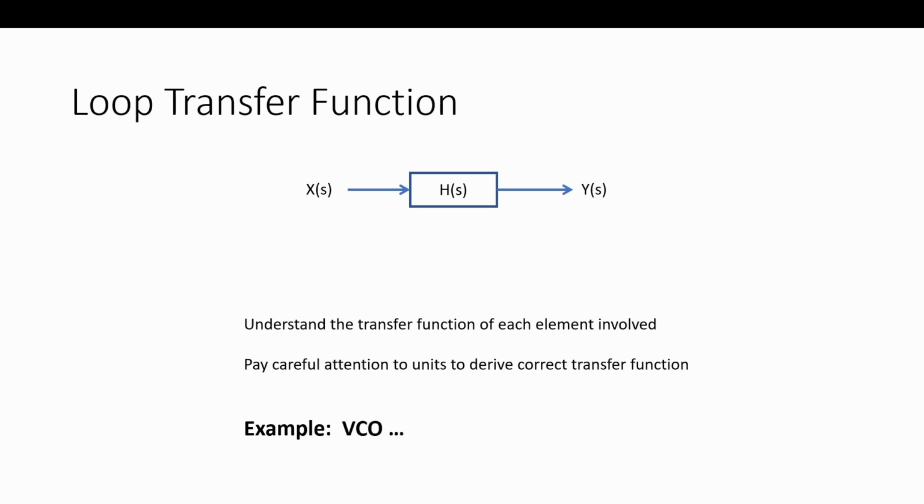Or if that component is temporal or frequency dependent, if it's like a filter, then you're going to see S's or Z's show up depending on if it's continuous or discrete. So that's the difference. If it's a component that is instantaneous within where we care, close to the loop bandwidth of what we're doing, then we can treat it as a fixed gain and it's a unit translator. You're going to see that. But if it's not instantaneous, if it has a response time within our time of observation, then you're going to see S's and Z's show up as part of that component.